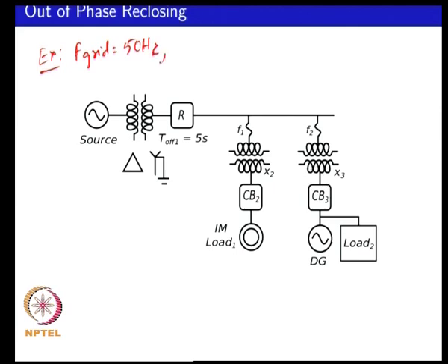And you assume that after the recloser opened, the loads with your DG in the island, the frequency shifted to some other value, say the system frequency shifted to f of the island, say 49.9 hertz after disconnection of the main breaker, and the recloser stayed open for 5 seconds and then it tries to reclose.